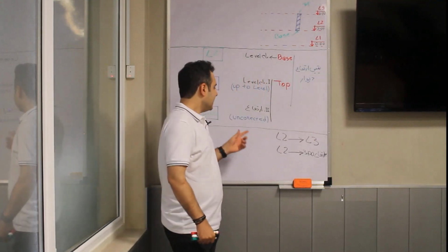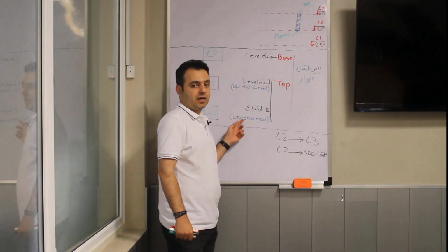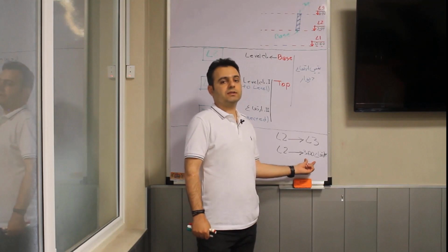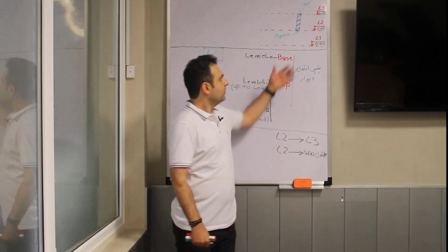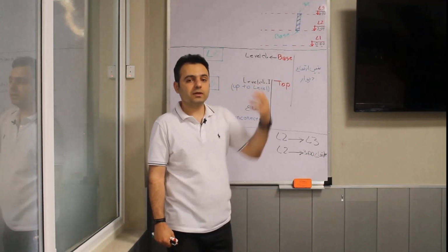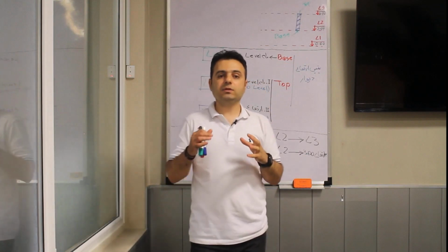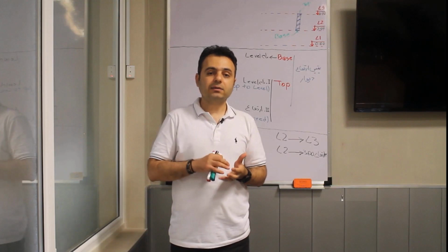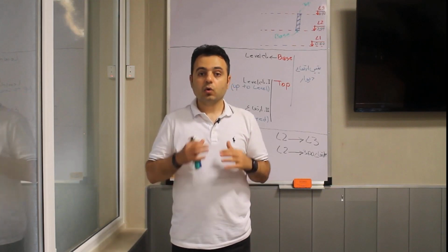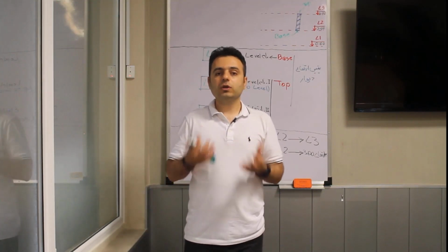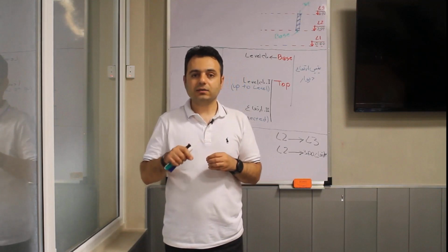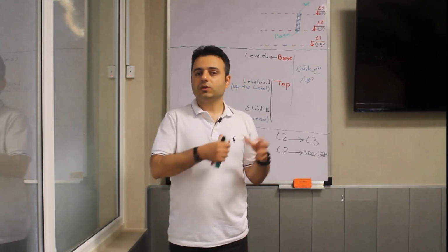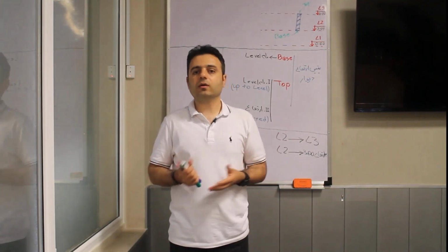So, if you have used the unconnected method, you have given a height to your walls, for example 3 meters. Now the height is going to be 4 meters. What should you do? You should go and select all the walls that you have drawn and then change the height. And that selecting is too challenging because in the middle of your job you might choose other objects with it, and it's actually a difficult thing to do.